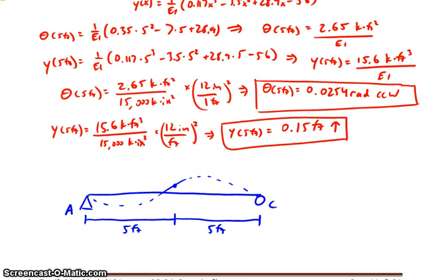Hopefully that makes intuitive sense to you. Go back and see if that makes sense by just thinking about the original beam and that point moment. That point moment is a counterclockwise point moment, and it makes sense that that would cause the deformed shape to be going diagonally up and to the right at midspan. So take a second to think about that and make sure it makes sense to you.